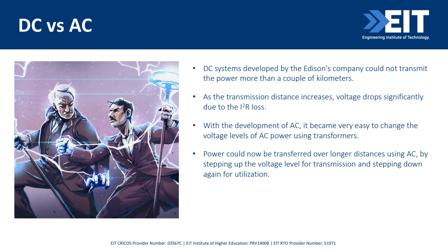And for a very long time, we relied on AC transmission and AC distribution systems. But we know that there are challenges with AC transmission. There are actually too many challenges, not just the synchronization challenges with renewable energy, but also typical AC power has its own challenges like inductive losses as well as corona losses. But we didn't have the means in the past to use HVDC.